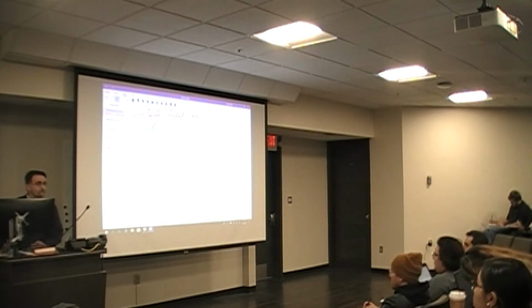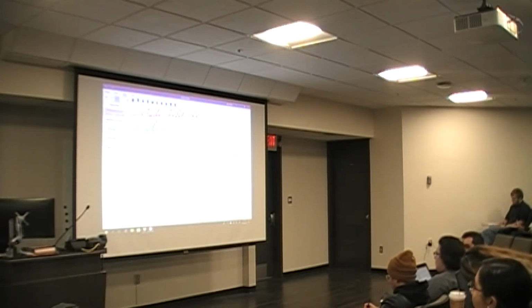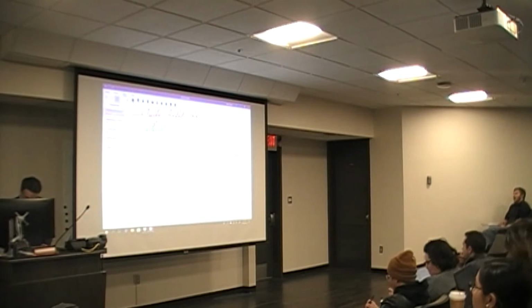This, for instance, is still called poorly graded material. Doesn't mean that it's not a good gradation. It has different applications. We have to figure out what the application for that is. All right. The other gradation that we have here is